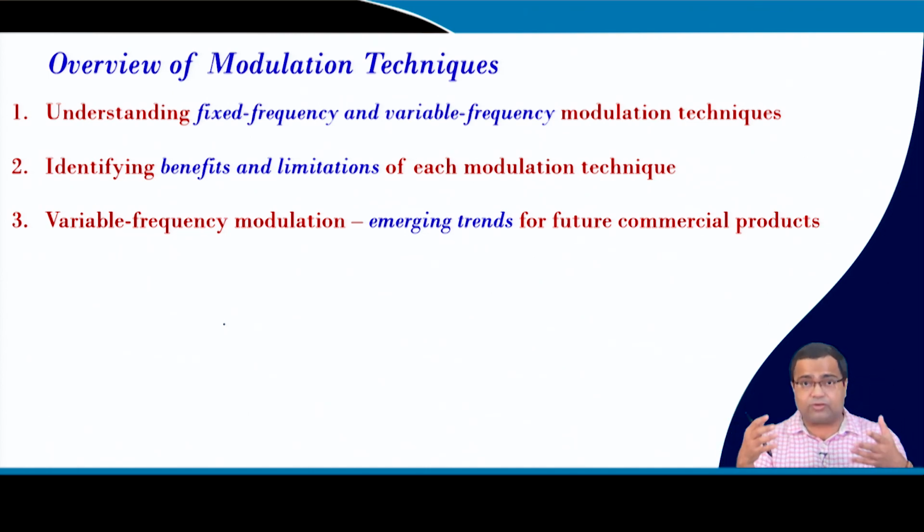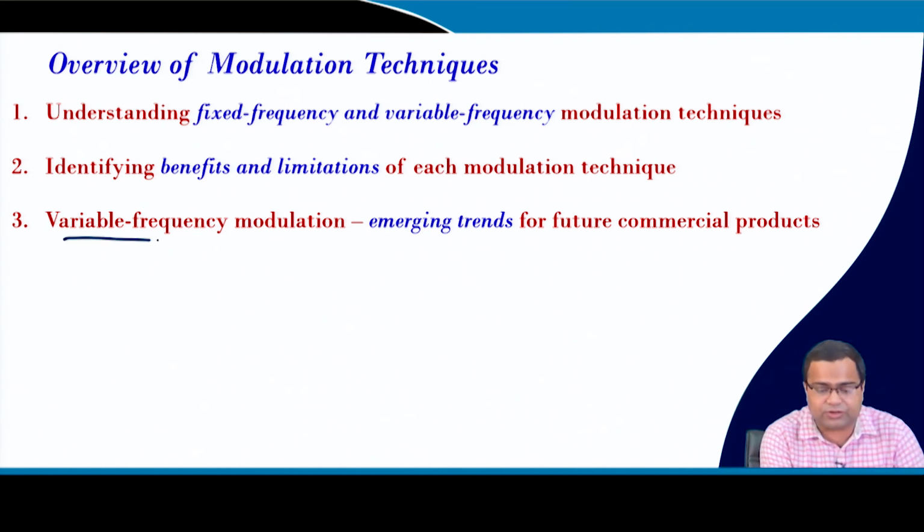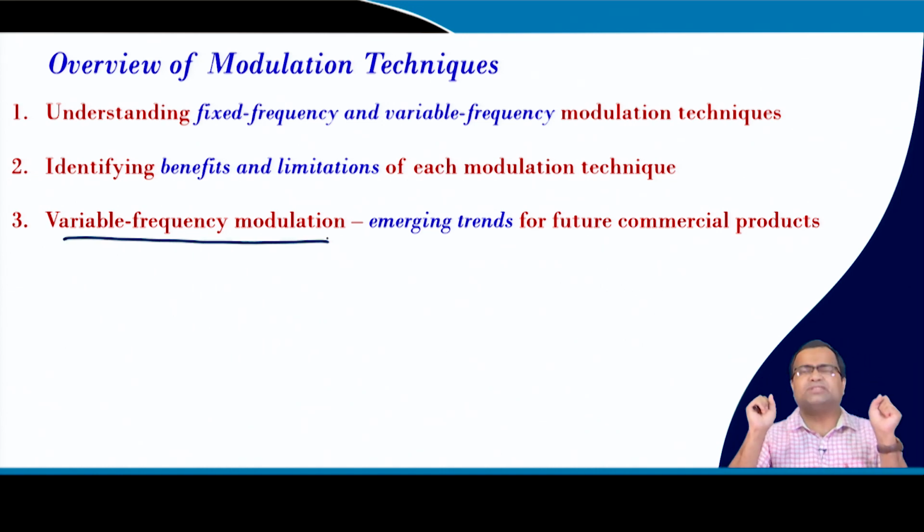I mean, it is going to be useful, and using a digital control architecture we can make things much better, because one of the limitations of variable frequency control is regulating the switching frequency. But once you go to digital control, you can easily program the switching frequency inside the digital platform, because you have an inherent all digital PLL.